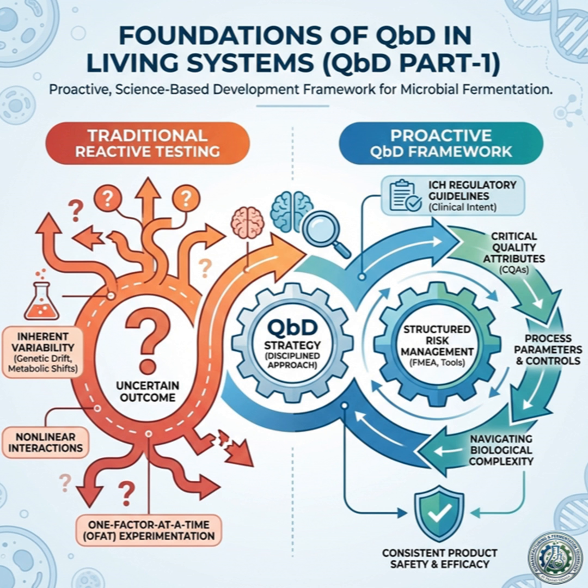The source material identifies a very clear villain in this story, and it's not the regulators. No, it's biological variability. The central constraint of the whole industry. Absolutely. The text makes a really interesting comparison between a chemical reactor and a fermenter. If I'm running a chemical process, my catalyst is, I don't know, platinum. It sits there, it does its job. It doesn't have a bad day. Right. In a chemical process, your reactants are defined, your stoichiometry is defined. The variability comes from physics: mixing, heat transfer.